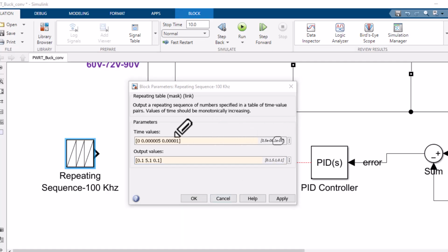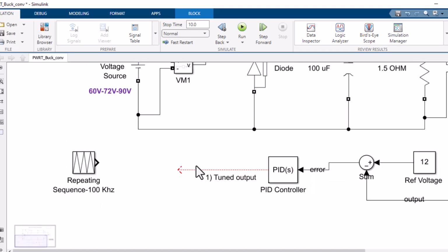That will be the maximum. Half of the maximum will be mid, so I will be getting the triangle wave. I will show you the waveform also, not to worry. This triangle wave has to intersect with the PID output, which is my second wave. To generate the pulse, we should go for the intersection method.